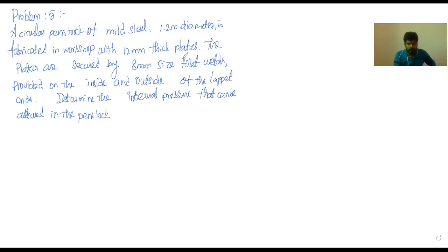The 8 mm fillet welds are provided on the inside and outside of the lapped ends, so inside they have done one weld and outside one weld, each 8 mm thick.